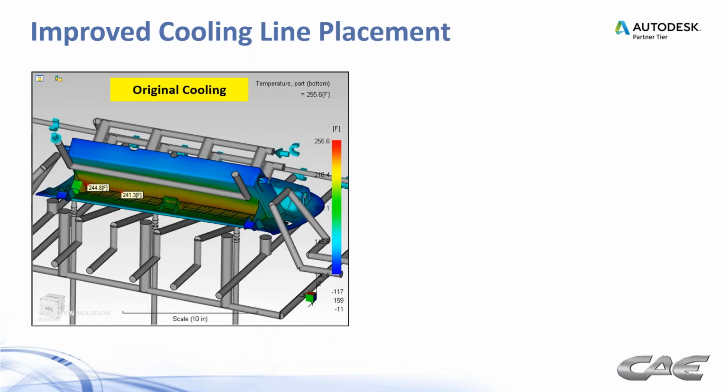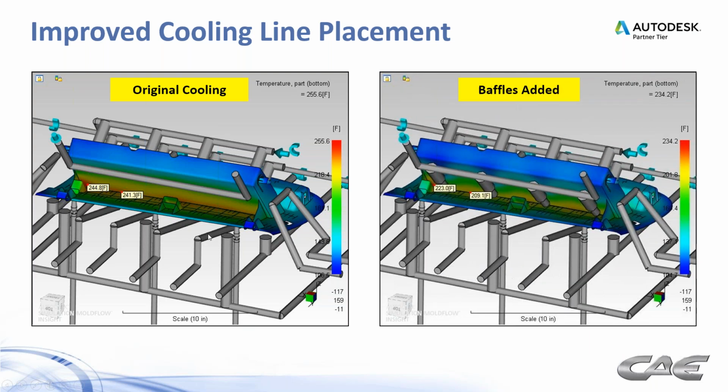So just with standard conventional tooling, maybe we have a cooling design that looks like this. We've got a very tight piece of geometry here, very tight angle, and you see a temperature buildup in those corners way higher than the temperatures of the rest of the part. We do have a cooling line there, but we're not yet getting the cooling very close to that internal corner there.